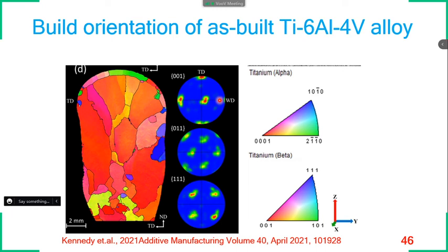From electron backscattered diffraction, we can generate the inverse pole figure through the Kikuchi pattern. The inverse pole figure gives the information on which direction the grains are oriented. Especially during complex solidification, we are not sure in what direction the grain will orient.